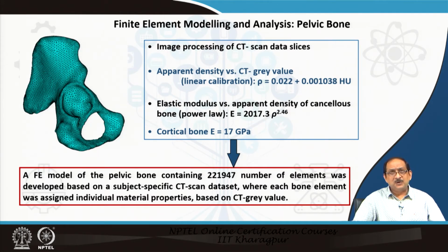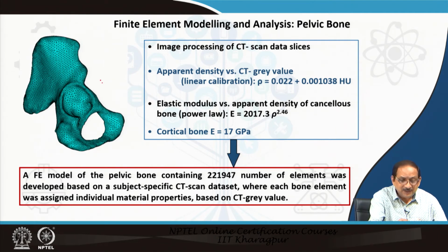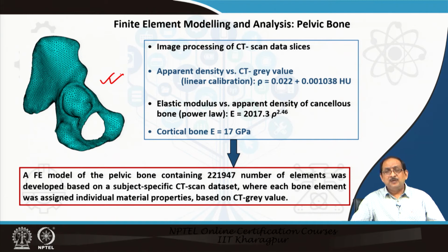Let us now focus on the finite element modeling and analysis of a pelvic bone. Herein I reintroduce the slide that was discussed earlier in lecture 6.2, the procedure of development of a finite element model of the pelvic bone based on CT scan data. From image processing of CT scan data slices, we can obtain a solid model, then we can generate the mesh to develop a finite element model.